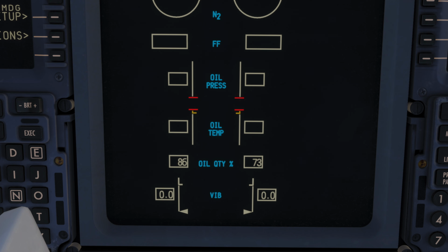The one thing that the oil system is important for is to avoid metal-to-metal contact inside the engine, which will lead to an almost immediate destruction of the engine. Therefore, the most important thing here is to avoid those rotating engine parts touching one another. That is what the oil is doing, and the pressure and the temperature gauges just give you an idea of how well that is running.